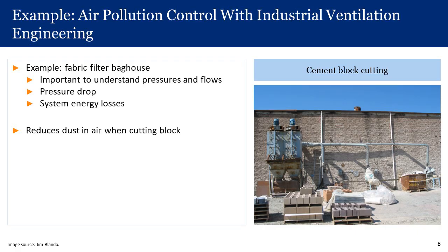They're going to stop filtering the air. If I do not control or design the ductwork properly, it's possible that I might not be able to carry the pollutants from the cutting saw into the bag house, therefore not controlling or capturing the air pollutants. So you do have to maintain these and operate control devices properly, which means that while they can be very effective, they do need to be maintained and operated properly. Otherwise, they could become very ineffective.